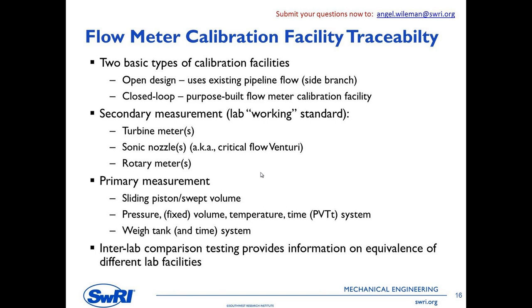In a closed loop facility, because it's purpose built, because we actually have to put gas into the loop to make it work, you can test at any pressure, or whatever pressure the facility is capable of. So depending on the meter type and depending on the application, there are certain advantages to closed loop facilities. The biggest downside of that is you have to produce all the gas flow yourself, so it tends to be a little more expensive to generate that flow.